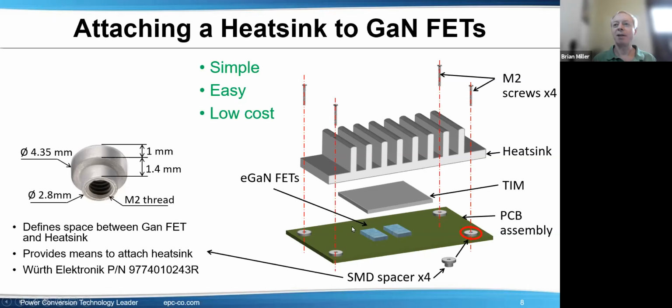This has the advantage of maintaining a constant gap. It eliminates thermal stress from the top of the FETs, and it's just a good control system for constant pressure and repeatability. So it's relatively simple. It's easy to implement, and it's low cost. Use standard heat sinks.